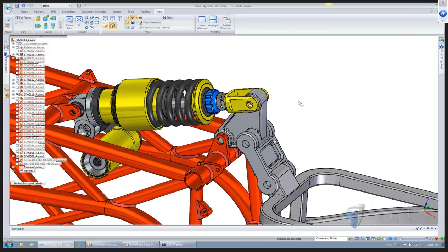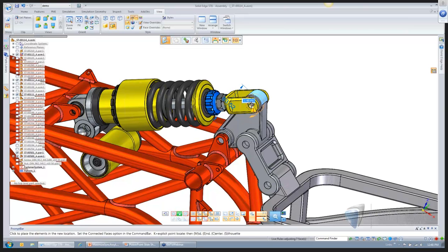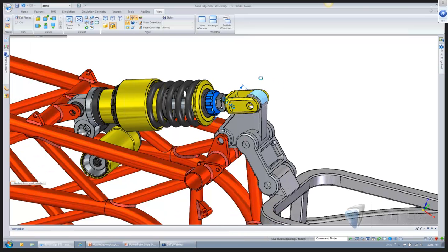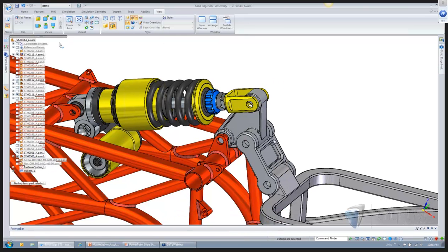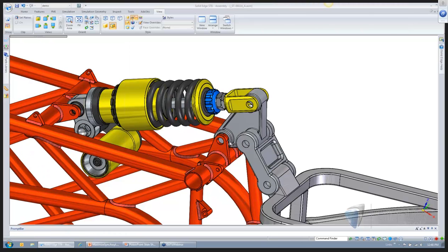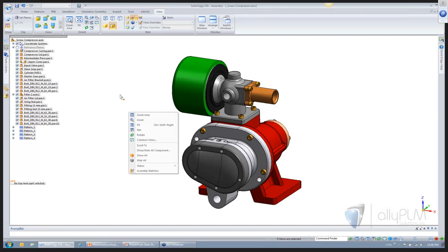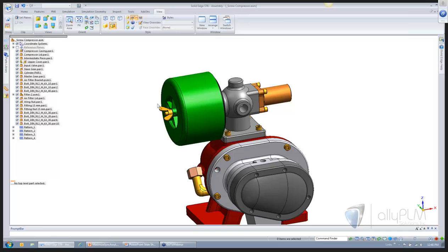We're able to make those edits on the fly by honoring our part priority, our face priority, and you'll see that we can make modifications here. And not only do we get to modify the part, we get to see real time the kinematic relationships that are being updated in our assembly. I think that's the benefit of Synchronous that's very oftentimes under-discussed, is we often think that Synchronous is a part-level tool, and we need to be thinking of it as a design tool. And how do we use it to help us in our design approach?